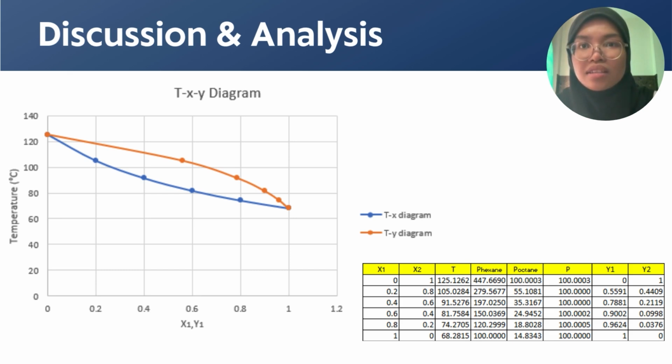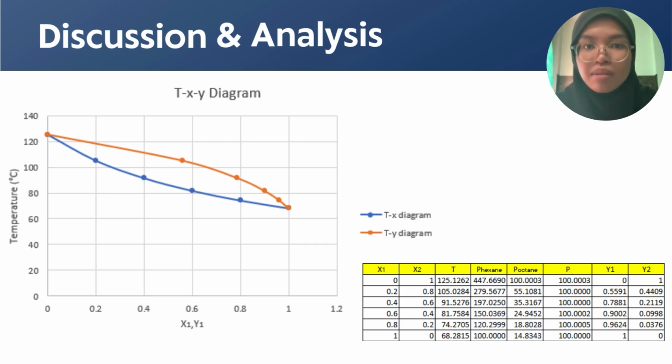So at 87.8 degrees C and 100 kPa, we can partially vaporize the liquid mixture, then condense the vapor to collect more hexane. This is how the separation is achieved, using the difference in volatility clearly shown by the gap between the two curves on both diagrams.